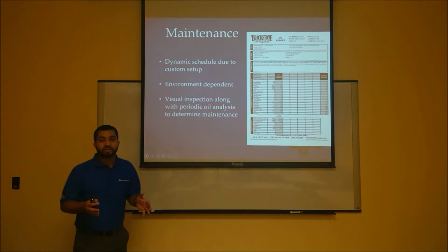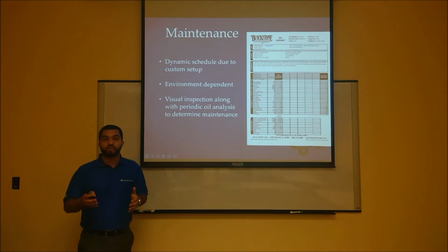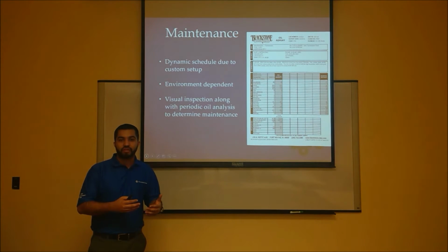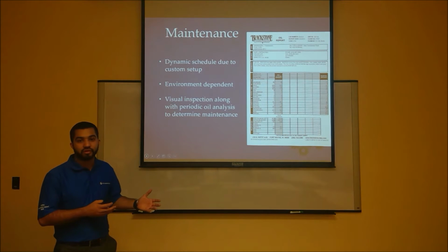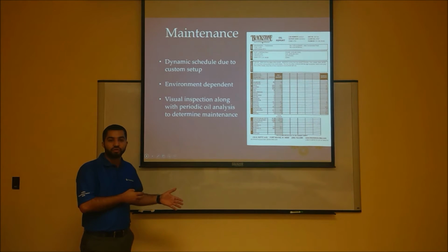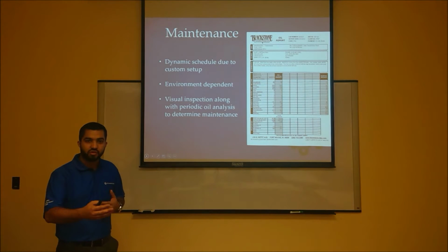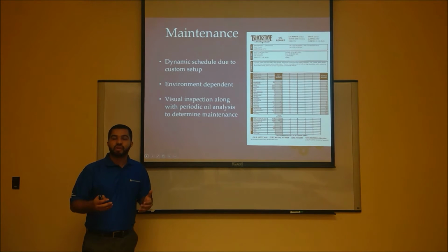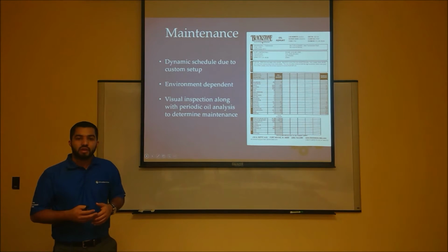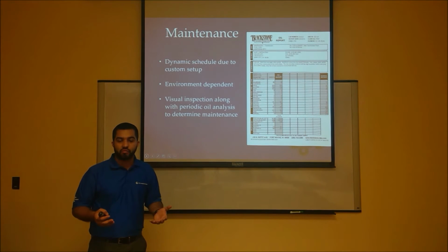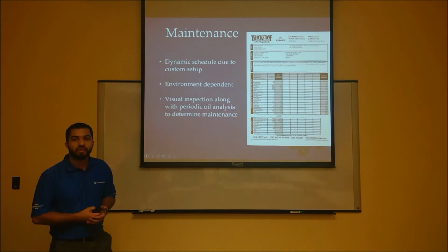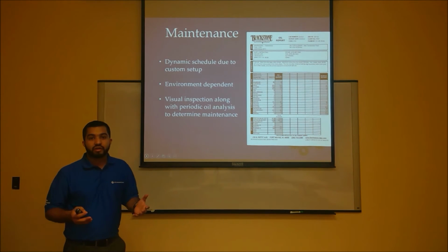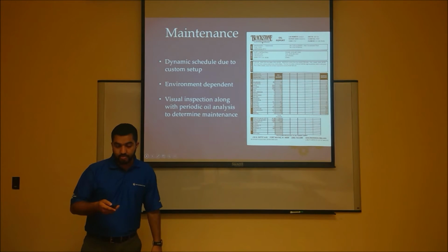Now, developing a maintenance program is very important to this gearbox, right? Because we need to be able to set up an oil change program for this, and we can do this by using a laboratory that can analyze our oil and tell us, hey, you need to change the oil at this interval or whatnot. We also need to take into account the environment that it is operating in. If it's in a hot, dusty environment, it will require more maintenance than if it works in a clean environment at room temperature. Also, periodic visual inspections are required for this gearbox.